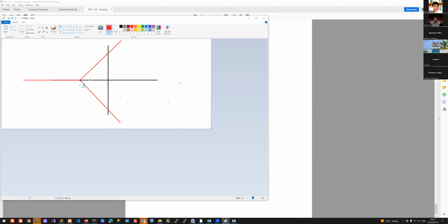So from this alone, we can say, well, on this route, we don't get any instability. Along this route, there is a point where we do enter the positive right-hand plane. So it does look like we will become unstable for certain values of k. So we need to find these points.